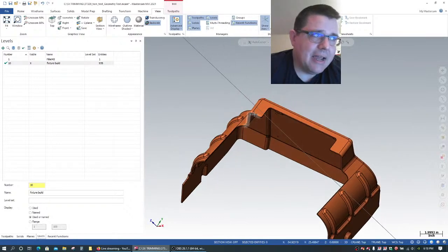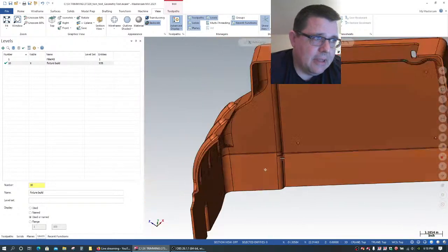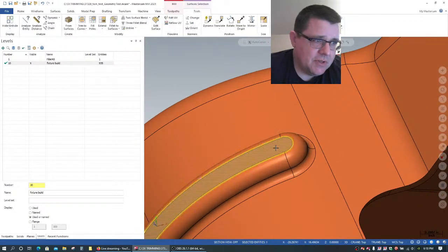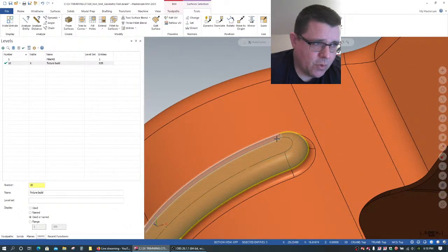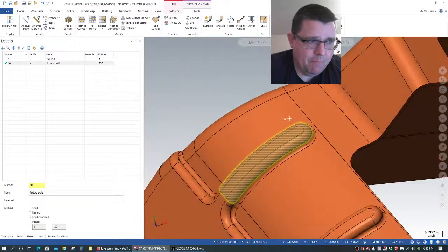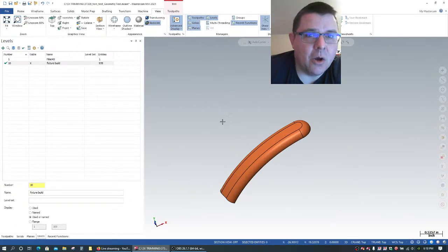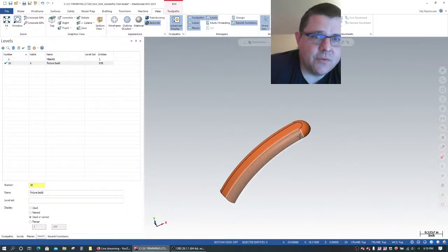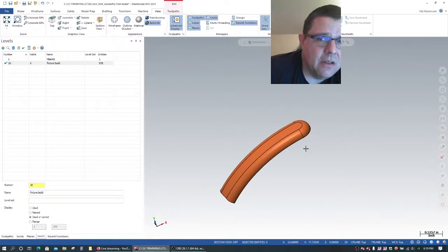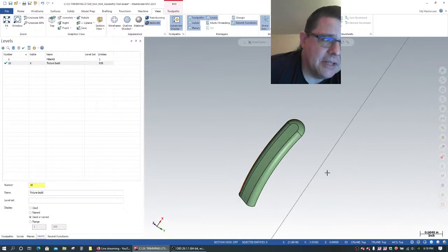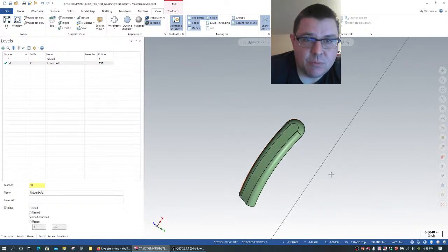And what the backside allows you to do, if I grab just a couple of surfaces, I'm going to grab these, say, 4 surfaces right here. I'm going to select them. And then I'll do Alt-E on the keyboard. So that's Alt-E, Alt-Echo, so the E key. And by selecting those 4 and then pressing Alt-E, I've temporarily hidden all of that geometry. So I've only got these 4 surfaces displayed in Mastercam. Everything else is temporarily hidden.